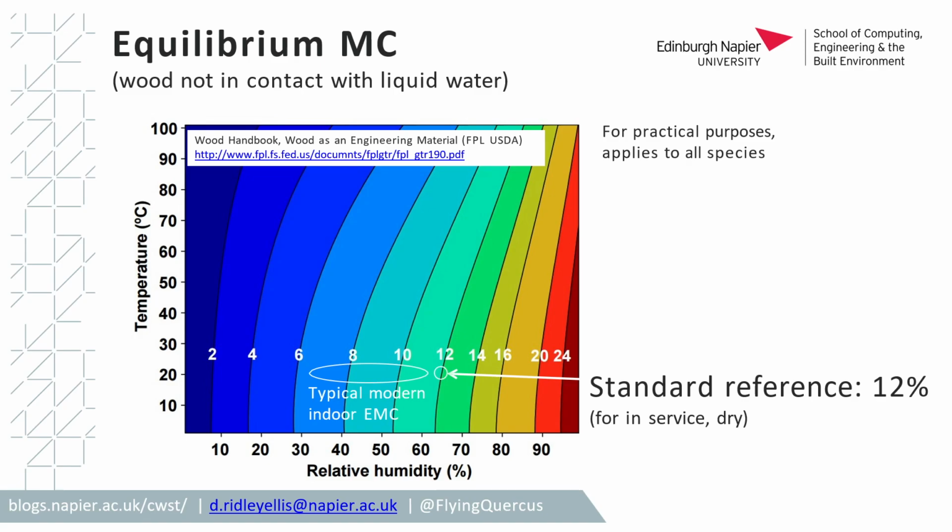That's a quick and easy way to get the moisture content. It's not as accurate as what you've done with the oven. That's a precise way of doing it. But we'll chuck it in a conditioning chamber and we'll keep measuring it every so often. When it stops changing and it's consistent, then it's ready to test. It would be roughly 12%.